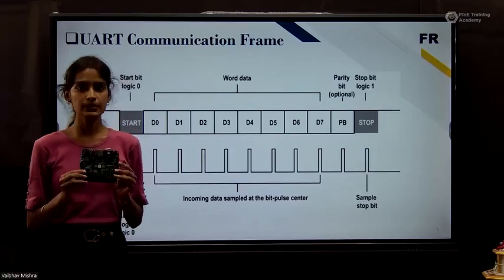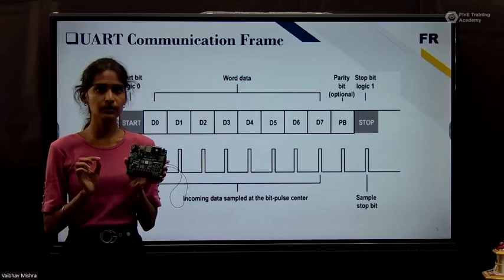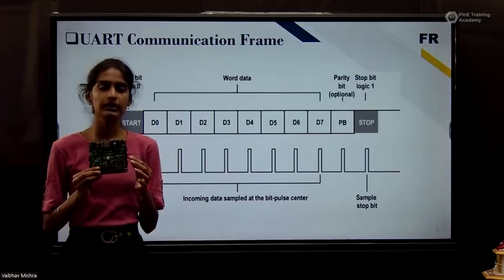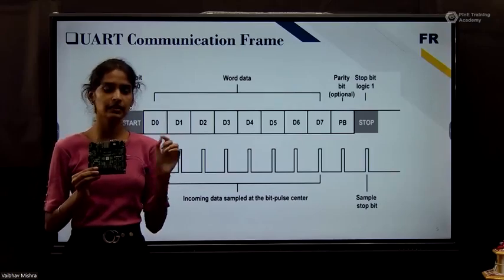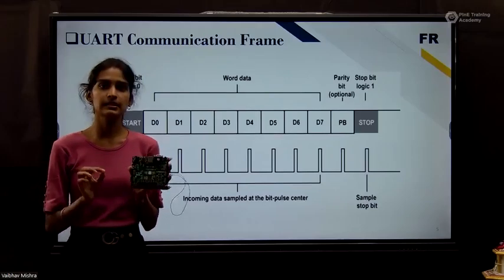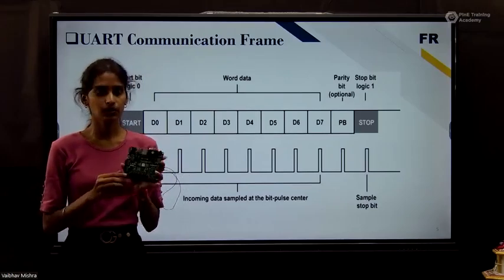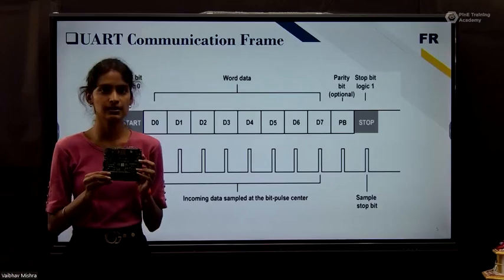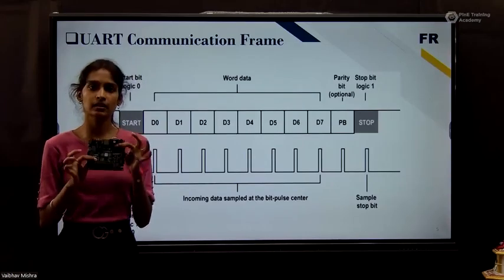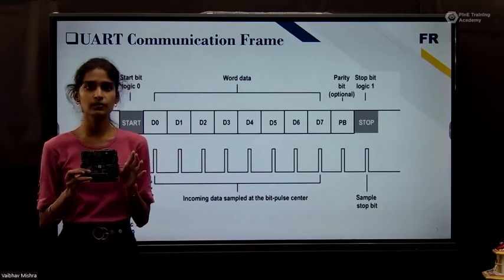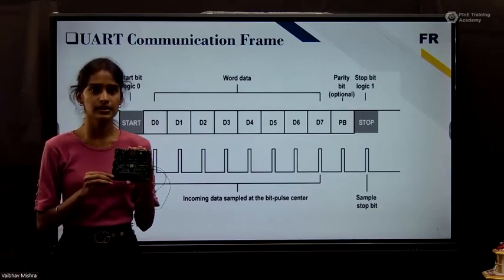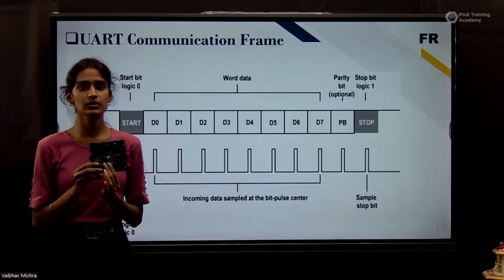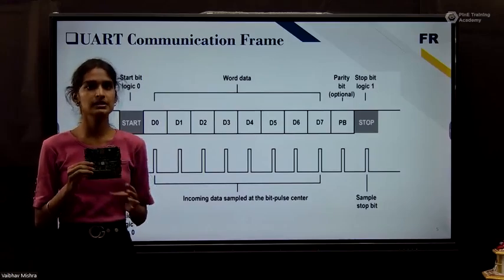Whenever the FPGA is programmed, firstly we give the input. Our input drives the switches, and after the switches, our input goes to the PMOD port, and from one end of the jumper cable, our data is transmitted serially, and at the other end, the data is received serially. After the serial reception, we can show our data in parallel form on the LEDs of the FPGA, or for better visualization, we can also see it on the 7-segment displays. So this single FPGA, this single device, performs both transmission and reception. Therefore, we can also call it a transceiver. This FPGA works on serial communication, which operates on the UART protocol. Therefore, we can visualize our UART transceiver using VHDL project on this single FPGA module.